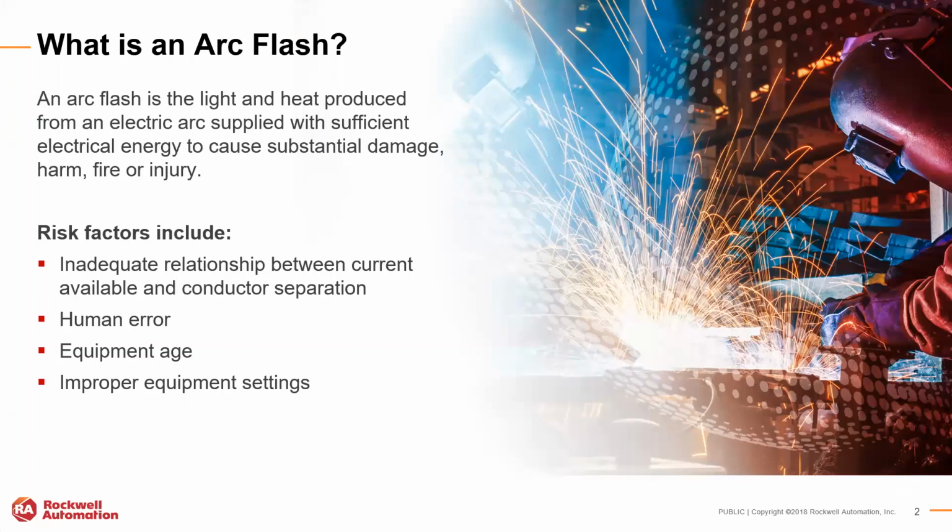Your equipment could have some contamination. It could be deteriorated or corroded, and that could lead to an arc flash event as well. So in summary, an arc flash event could occur via a manual or physical interaction from an individual working on an electrical enclosure, or it could happen totally by accident via an equipment failure.